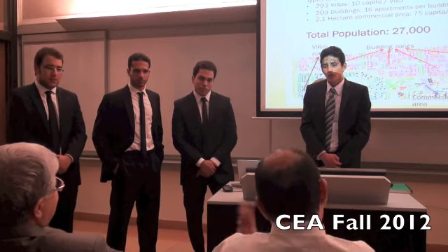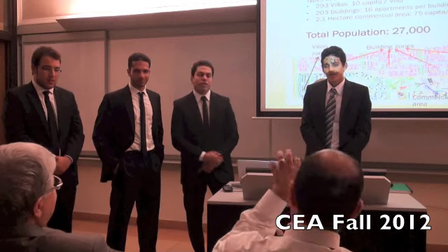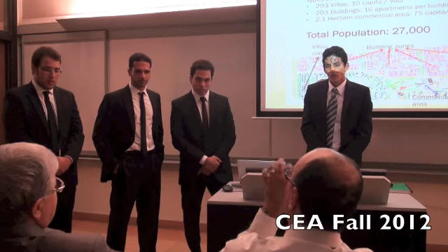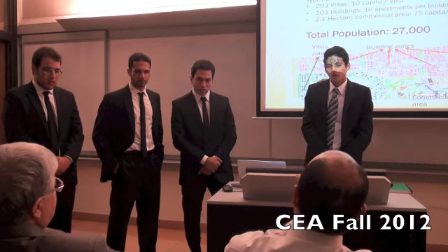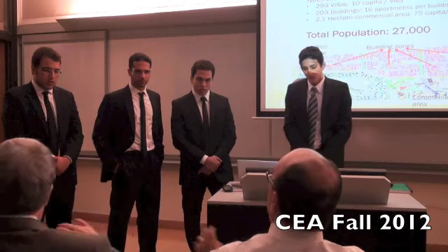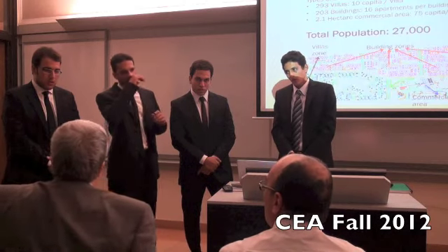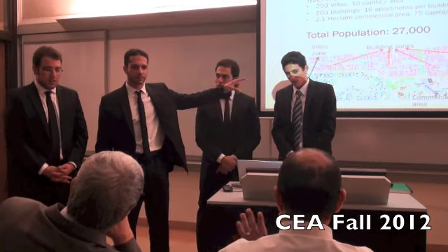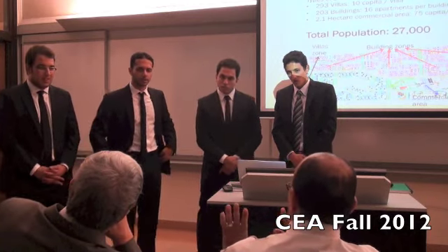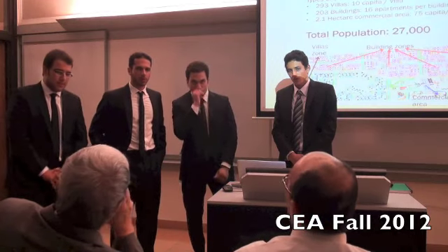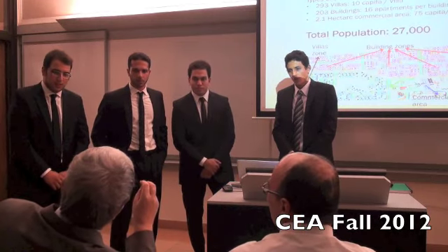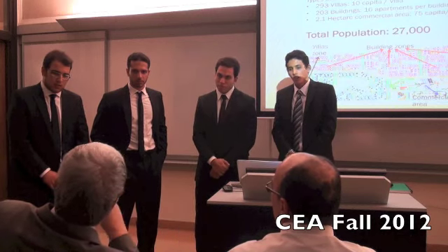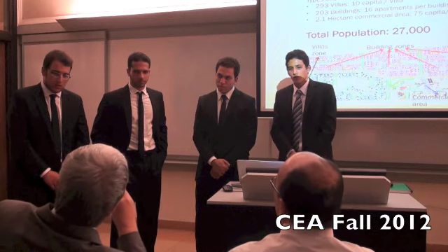Usually, I don't know about that design, it's not my area, but you have two pumps, right? One pumps the water there, then another collects the water, and then you need gravity again to the STP. Well, the pumping station is located at the lowest elevation, 73 meters. Please, just study it again. Justify why you have to use a pressurized pipe to transport the sewage back to the treatment plant. Why can a gravity pipe not work?